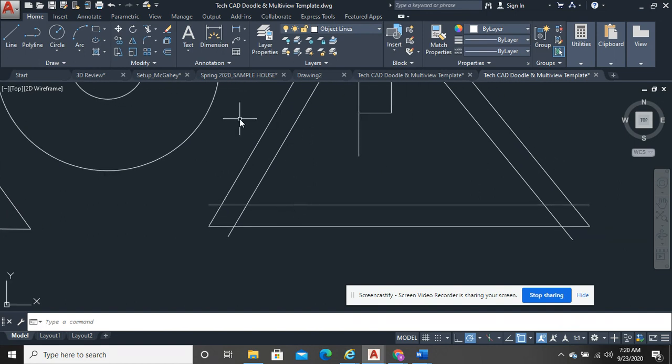He said, go ahead and pull up trim. So I said, TR space. And he said, don't do anything else. He literally had to shout at me before I even clicked anything. Hit TR space. Don't touch anything. Now hit the right click button one time. Now go ahead and pick whatever you want to trim, and it will just keep trimming and trimming the whole time. That is all you've got to do.